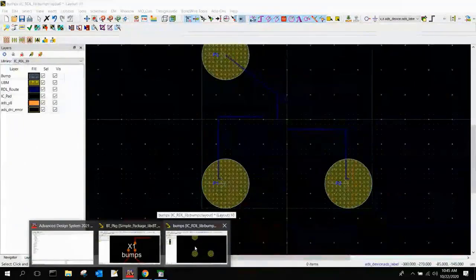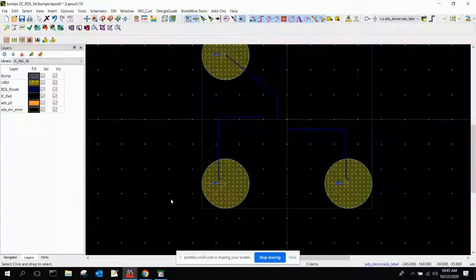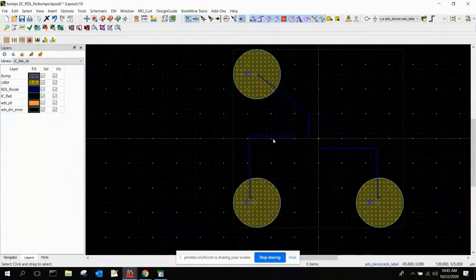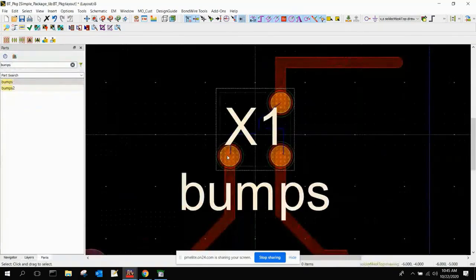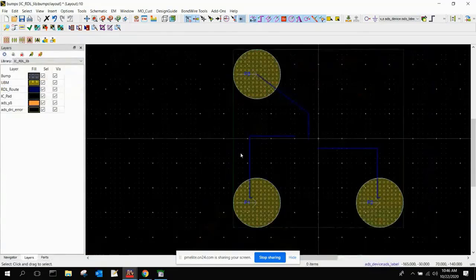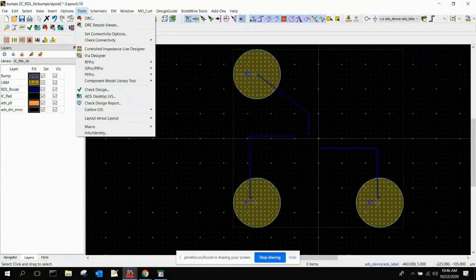So that covers simple, powerful, versatile. I think the other one is scalable. Scalable is pretty straightforward. If you're working in deep submicron nanometer types of processes, you'll know a lot of times the things that you draw with the metal are not what gets physically created. So there's some scale factors that take place in the mask. So I'll go remove this thing. Those scale factors are usually not hugely dramatic, but it can, of course, matter.